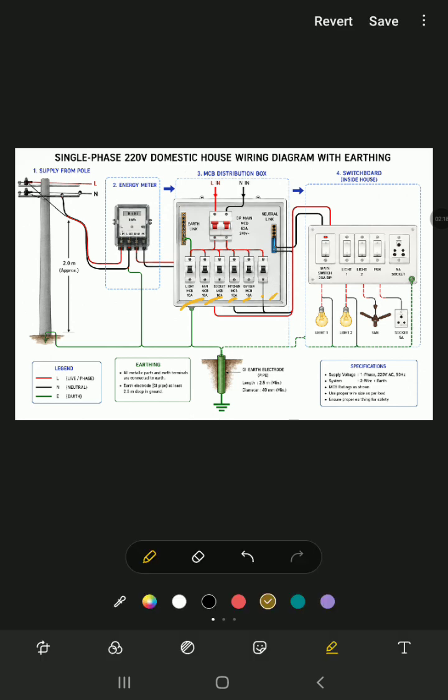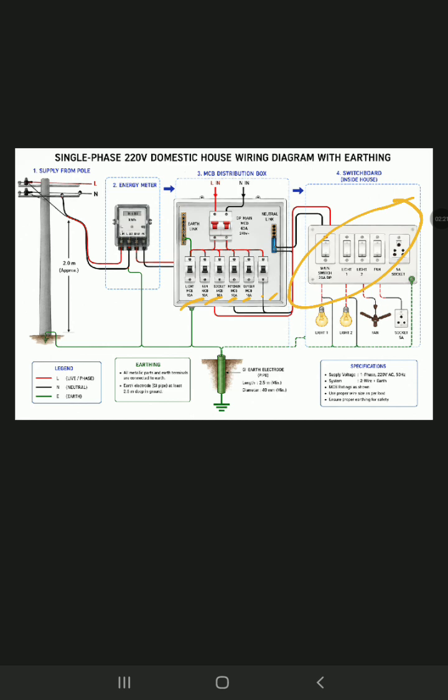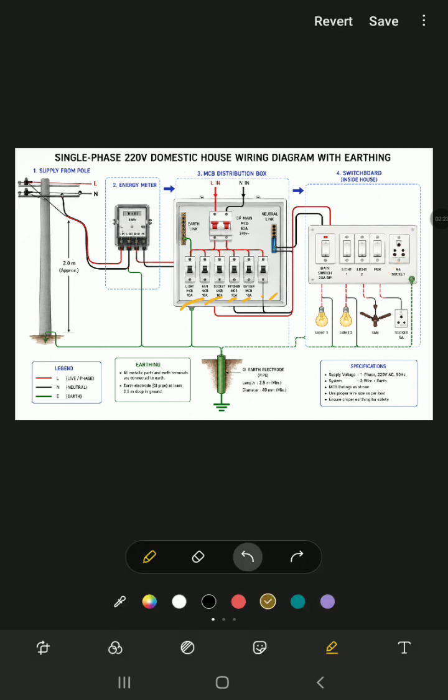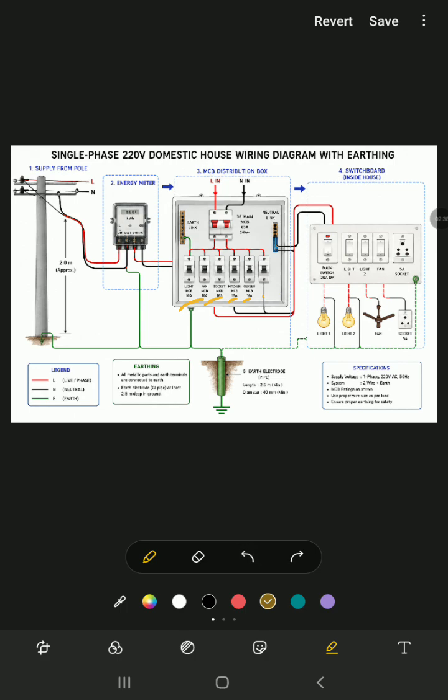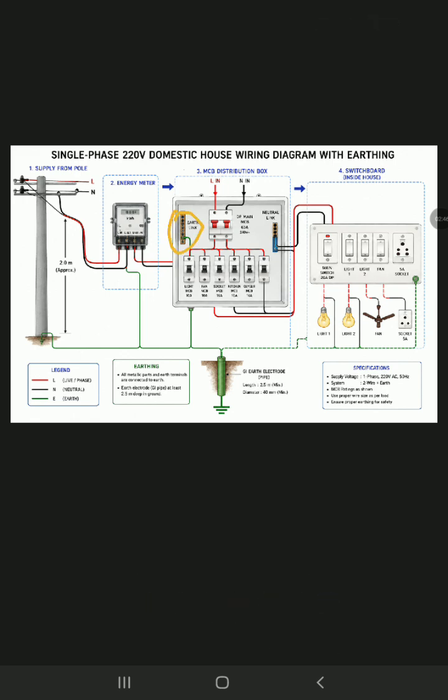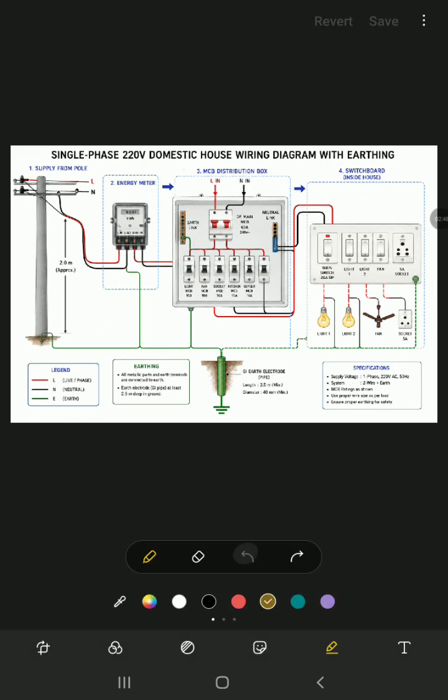These MCBs are based on rooms. For example, here only the room's MCB switchboard is given. We see different amperes for different appliances. For example, the light MCB, that means a room's light or anything, is 10 ampere. Here the geyser's MCB is 16 ampere or 20, and we can keep up to 40 ampere each based on our current load. Here we see an earth link also, from which we can take direct earthing. Generally we find earthing in our sockets, but we can also take it here.